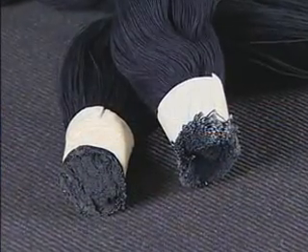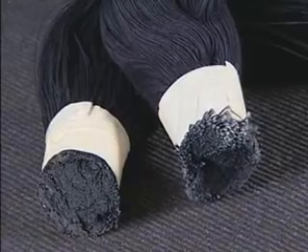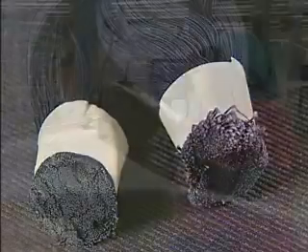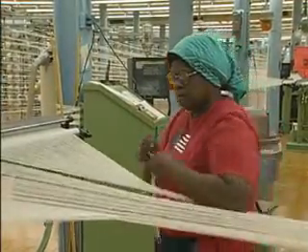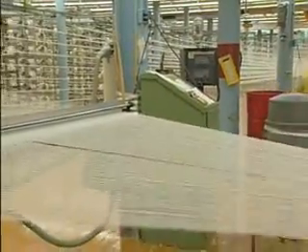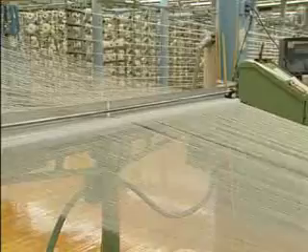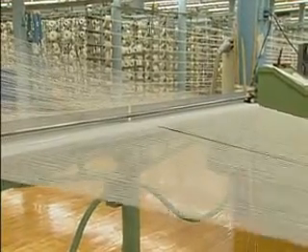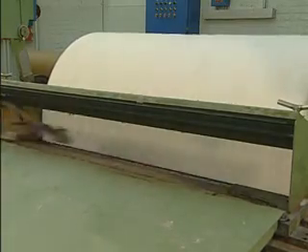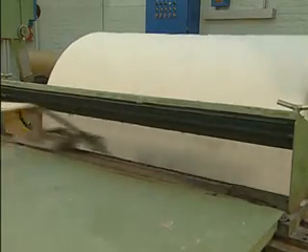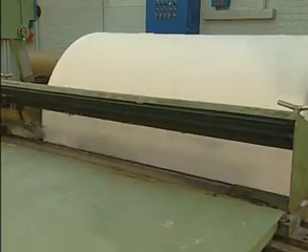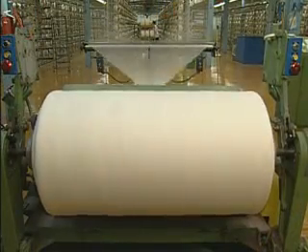For some special types of yarn-dyed warps, such as indigo for denim, a system called rope or ball warp dyeing is used. If rope dyeing of yarn is to be performed, then ball warps must be manufactured. Ball warps are made using a creel that is set up as with other forms of warping. However, the headstock is set up differently in order to condense the sheet of yarn into a rope. The sheet of yarn is passed through a trumpet-like device to collapse the yarn before it is wound onto the ball. The yarn is then wound onto the log like a huge package of yarn.